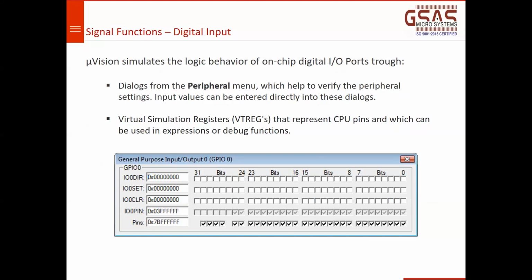And an interrupt is generated through the pins: only when a particular pin of a processor goes high or low is the interrupt generated. So through this pins option, you can see, because the interrupts are usually multiplexed with the GPIO pins of the microcontroller, you have to go through the architecture manual and see which particular port pin is multiplexed with the interrupt, and that particular pin you can make high or low, so that that particular interrupt will be generated.